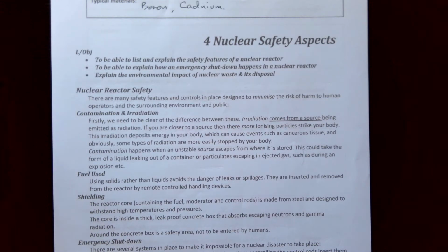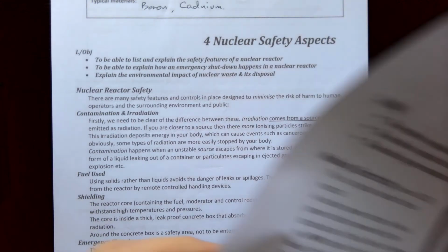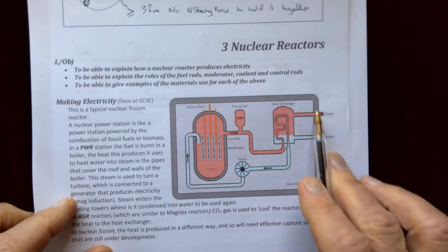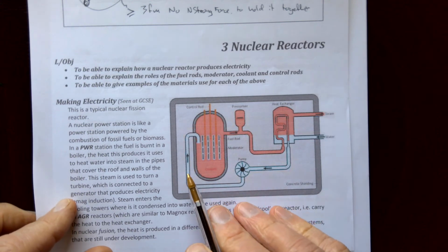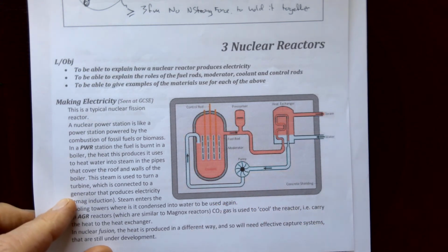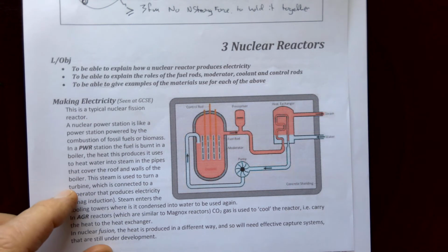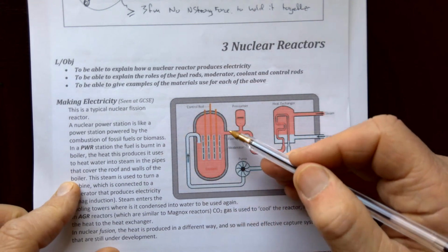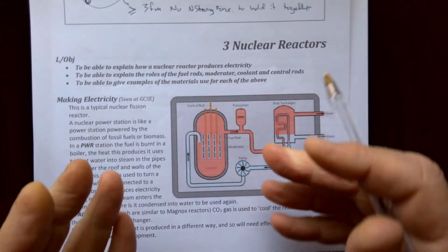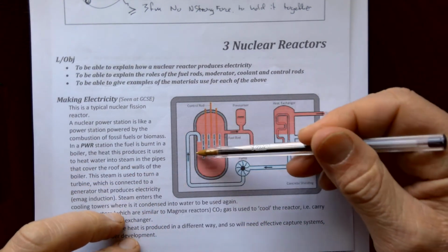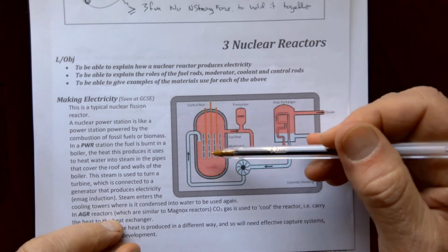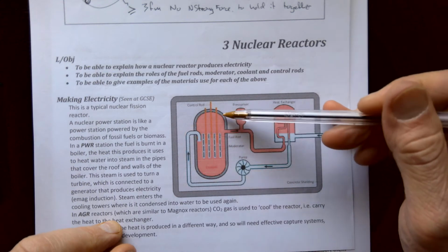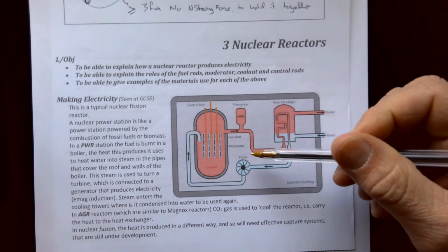So if they were in that reactor, or things that are surrounding it, so not in the reactor itself but in the reactor building, then those things have to be treated depending on their likelihood of radioactivity. So the casing around the reactor needs to be nice and strong, obviously, needs to hold shape and so on. So this is often steel. The steel is also being bombarded by neutrons. So the steel liner will become radioactive over time.